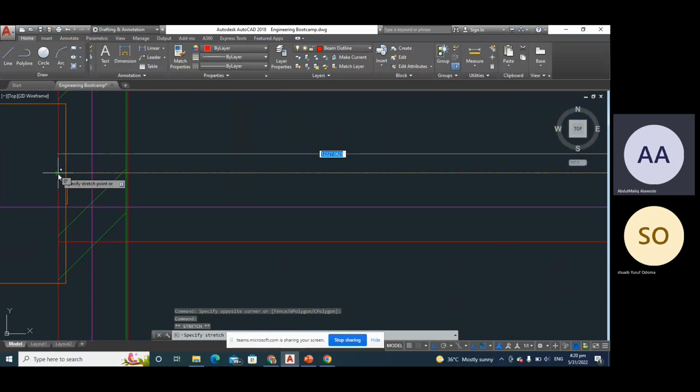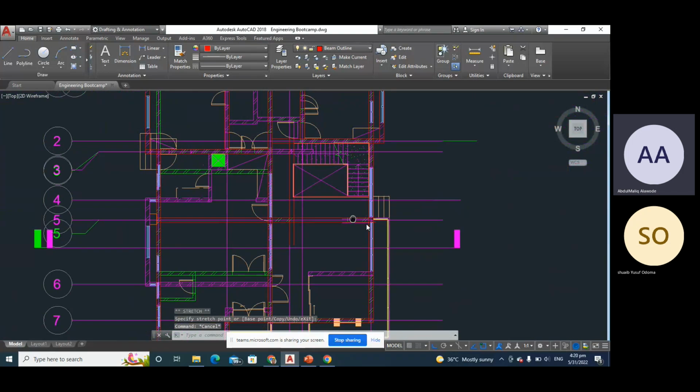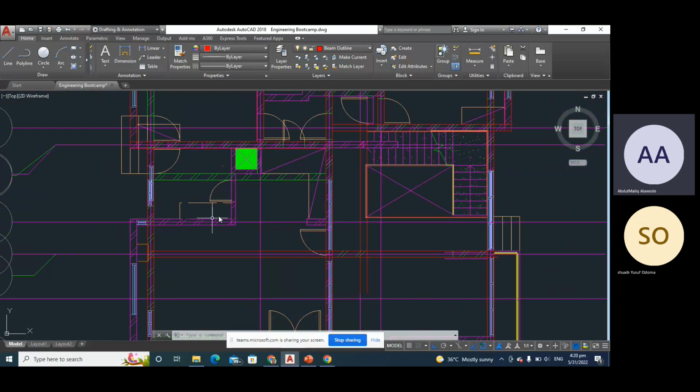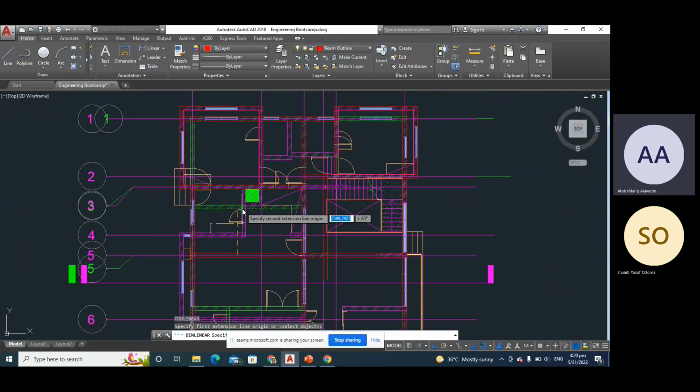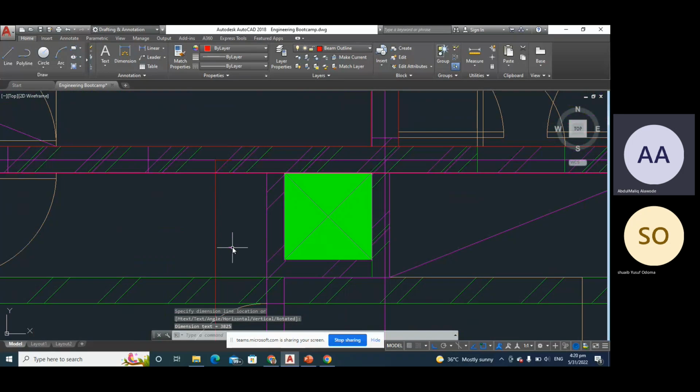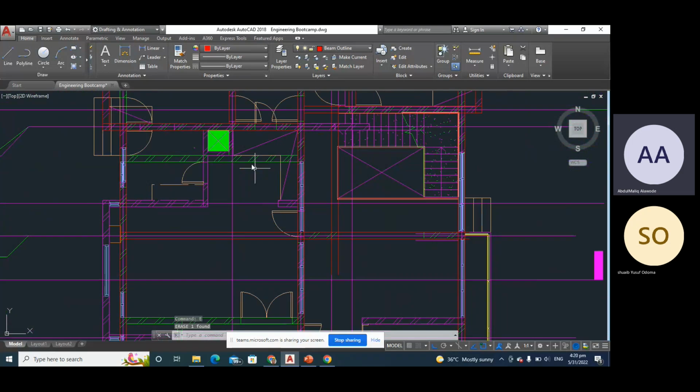So let's take this all the way to here. Is that okay? Then that means we have the whole of this as a single slab, which is not too big. In terms of LX, the LX is 3.82, so it's still fine. So we can leave this like this with this beam.